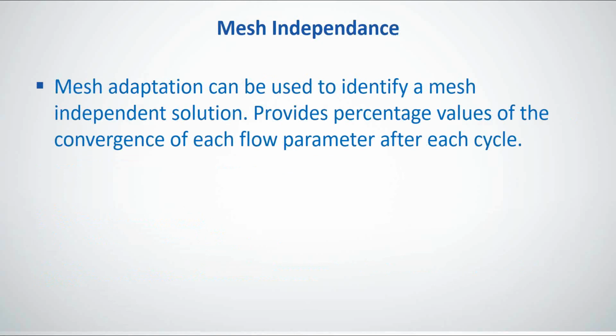As an end user who uses it every day, I really enjoy saving the intermediate cycles. Sometimes my second and third cycle will only marginally improve the results or the mesh independence, but the element count goes way up and the solve time gets way longer. If you tell it to run 3 cycles, it's going to run 3 cycles, but the intermediate one may be completely sufficient. So I like the save option. It's just a personal preference, and sometimes I go with that intermediate one.